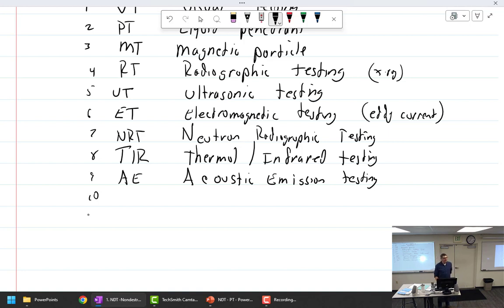Oh, I thought. That is literally taking microphones and placing them around something. One of the examples that I remember was a train car that holds the gases, the round ones. You'd put microphones all over it, then pressurize it and listen for a crack sound or some sort of emission coming from the straining of the metal. With enough microphones on there, it will pinpoint where that sound is coming from. Oh, you do that on a tank, you say? Yeah. That's cool as hell.